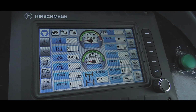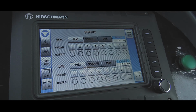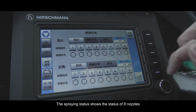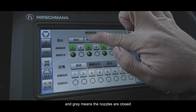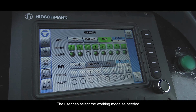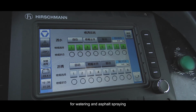Spraying control. This page can enter the control of water spraying and asphalt spraying. The spraying status shows the status of 8 nozzles. Green means the nozzles are open, and gray means the nozzles are closed. The user can select the working mode as needed, and the drive switch must be turned on for watering and asphalt spraying.